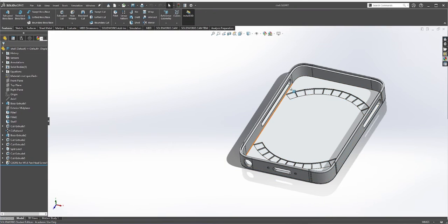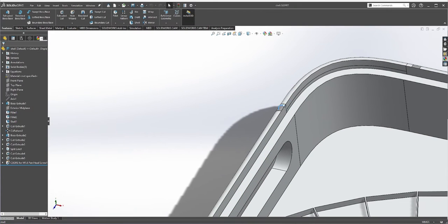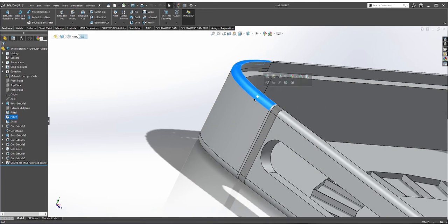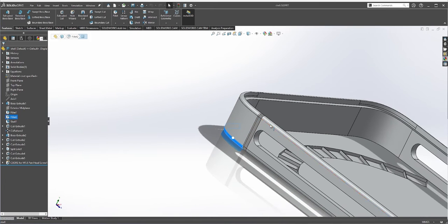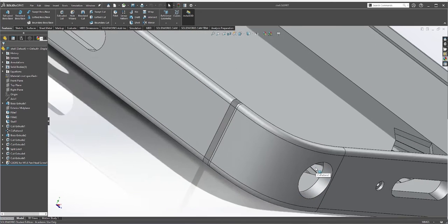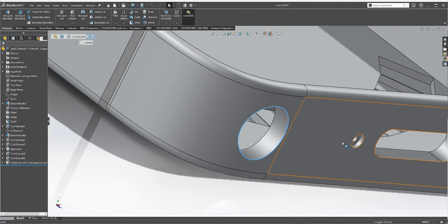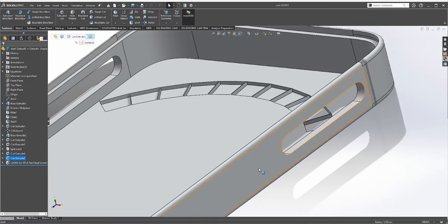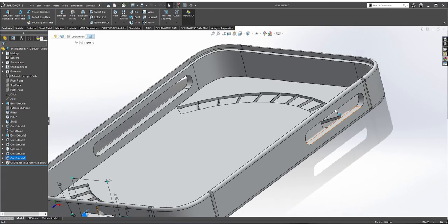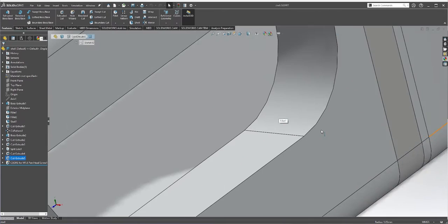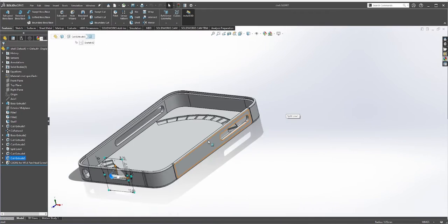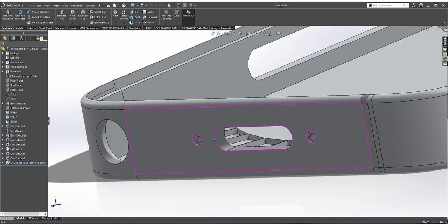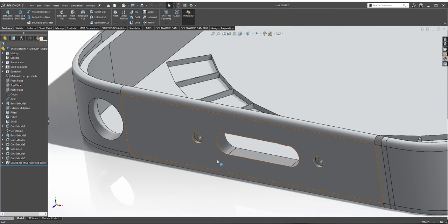To give you an example, I'm going to jump into the shell over here. And looking at the shell, you can see that I have added fillets. I've got fillets around the outside, over here, here, all around the edge. However, the corners that I want to remain hard, such as this headphone jack over here, the cutouts for the port, for the mounting screws, for the buttons, they're all hard edges. They haven't been filleted at all. If I zoom in, you'll see there's no fillet whatsoever. This is important because it reduces the polygon count of our model when we're importing into Cinema 4D.